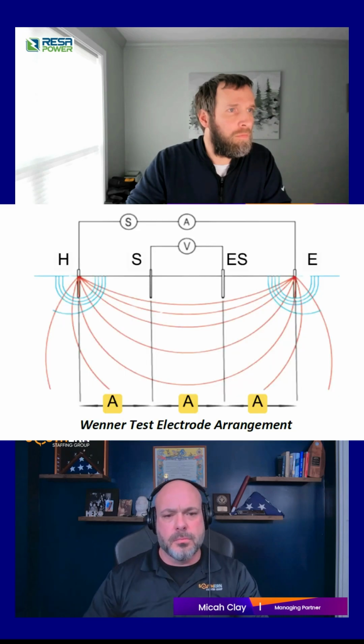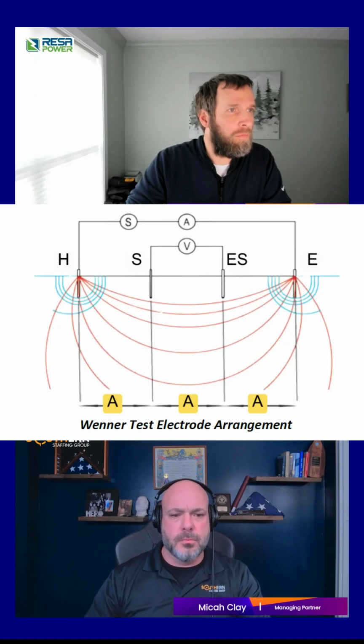Outside of that is soil resistivity testing. If I were going to put these in a more logical order, I would put soil testing first. This is going to allow me to perform a measurement of soil resistivity or resistance. We turn resistance into resistivity for then designing a system, or even maybe troubleshooting what measurement I'm receiving on a resistance to ground measurement.